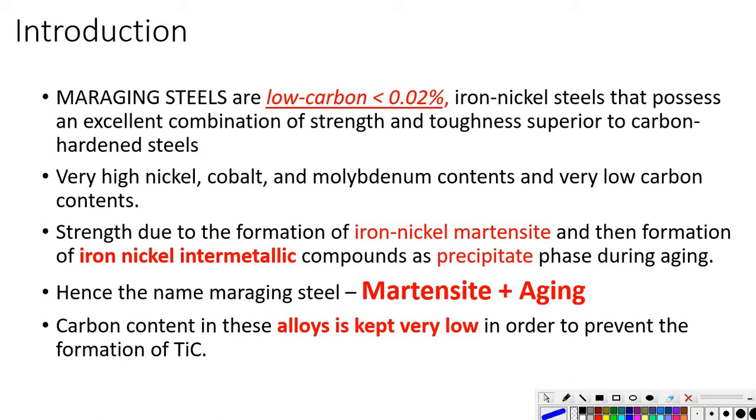So this is a steel. Maraging steel is a steel with a very low carbon percentage, but with a very high percentage of nickel, cobalt, molybdenum, and titanium alloy elements. So that is the Maraging steel, and that is the first part. We call this a steel. Even though the percentage of carbon is low, it contains carbon. That is why we call this material a steel material.